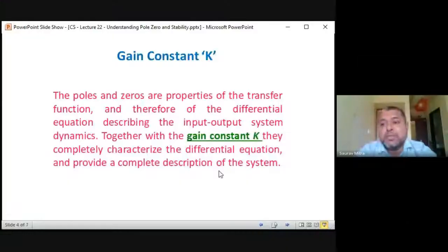So you give me a transfer function. Transfer function means there are three things now. Previously we were talking about transfer function as only output upon input. Now we will not talk like that. We will say that it is numerator by denominator, and roots of the numerator are called zeros, roots of the denominator are called poles, and it will be multiplied with a factor of gain k. K is nothing but the system gain. Now as we are going into the third chapter, next day we will start it. It will be k, poles and zeros.